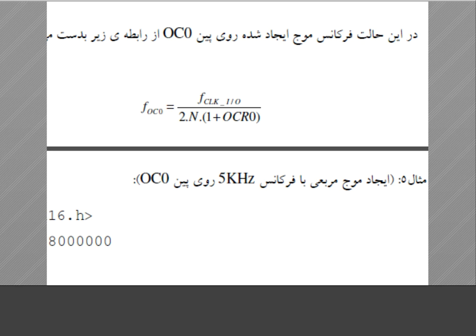The microcontroller works with the clock itself, for example 8 megahertz, but the timer section works with a slower clock: the clock itself, or divided by 8, divided by 16, etc. This is N, the prescale.